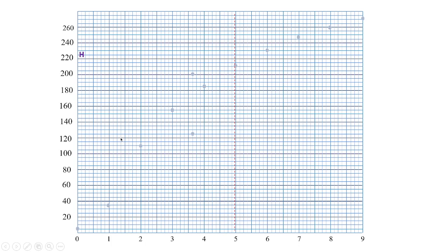Okay, so with these values of the tabular column, I get the OCC graph like this. The shunt field resistance line for 34 ohms is like this. You can see 34 is roughly taken over here. This is 20, this is 40. So between 20 and 40 the value will be 30, above 30 you have 35, and after that you have 40. So below 35 I have taken the value as 34. This is how the shunt field resistance line is drawn.